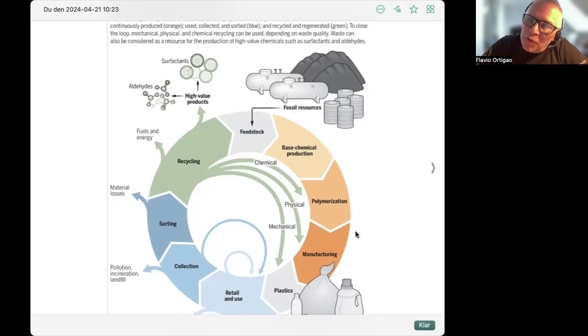So more often than not, the pyrolysis oil cannot be purified, or the purification of the pyrolysis oil is too expensive. I hear a lot that the pyrolysis oil is equated to naphtha. Well, this is not the case. Naphtha comes from the fossil oil, from the distillation of fossil oil. Pyrolysis oil is something else. Naphtha has a much smaller distribution. And the reactors for naphtha are very specific for producing naphtha. They don't take pyrolysis oil because pyrolysis oil is too complex.